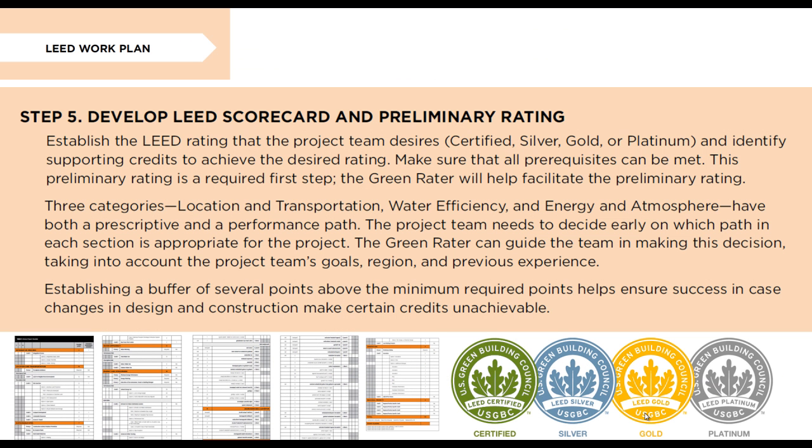Step 5. Develop LEED scorecard and preliminary rating. Establish the LEED rating that the project team desires, certified, silver, gold, or platinum, and identify supporting credits to achieve the desired rating. Make sure that all prerequisites can be met. This preliminary rating is a required first step.